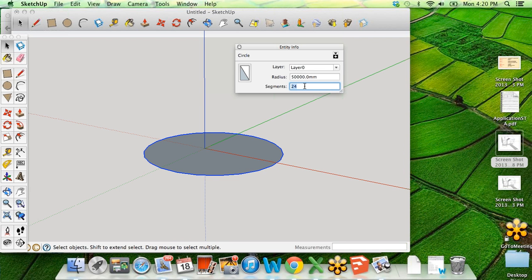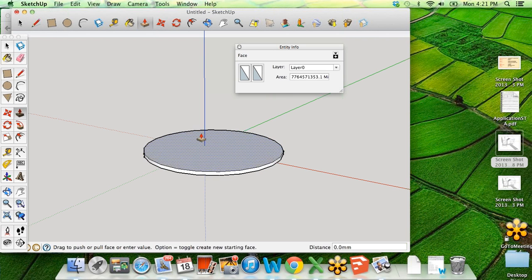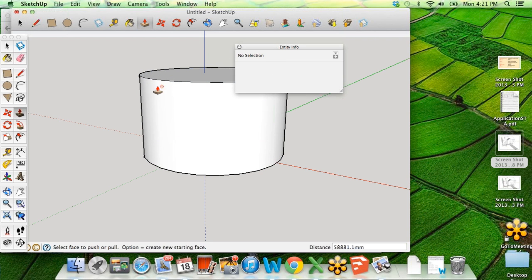That's 24, which is the standard, or just, how it starts. And then you can add way more. And the only thing this changes is if you're going to make like a castle or something like that, and you have your circles more specific, it's more data for the computer to know. So it can take a longer time for people to download that file, or something like that. For now, 24 is definitely fine. But what I wanted to show you guys was that let's build this circle. It's smooth. You can't see the different segments.